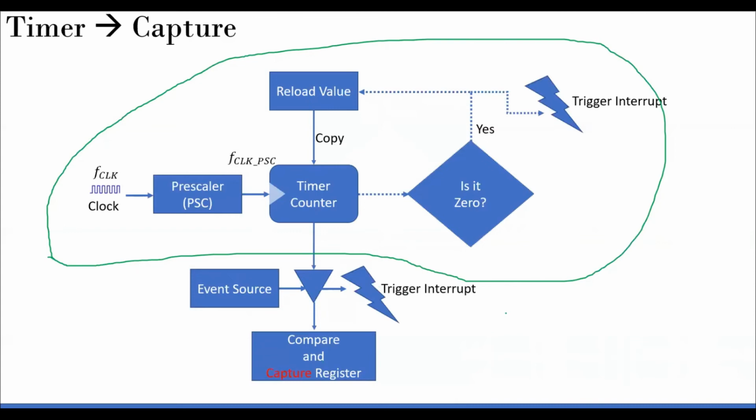Sorry if I confused you. So you store some capture value here. So at that instant of time when the timer value equals that value, an interrupt will be triggered. And then the corresponding input will be polled during that time. This is an example. So everything will remain the same, except the only thing is that the action will be slightly different now.